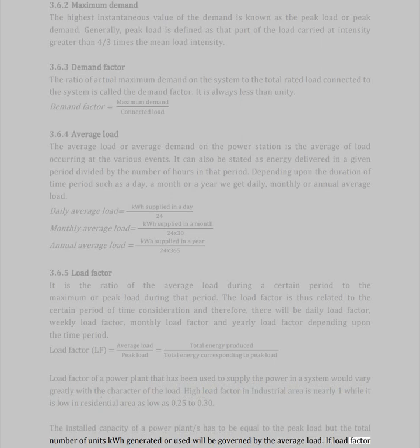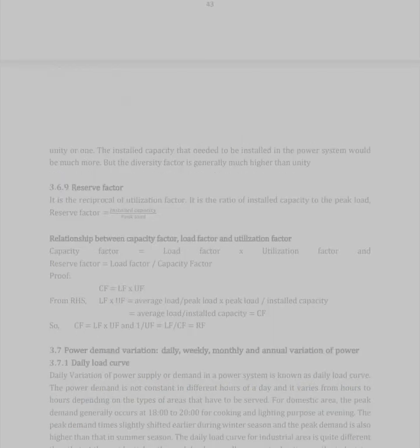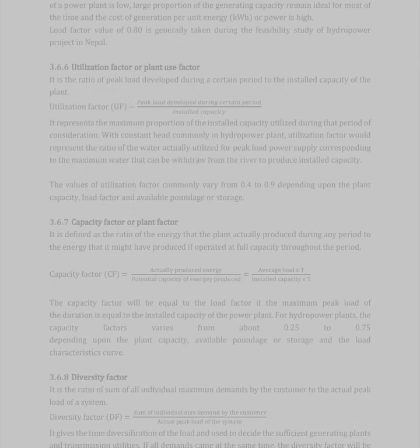If the load factor of a power plant is low, a large proportion of the generating capacity remains idle most of the time and the cost of generation per unit energy, kilowatt-hour, or power is high. A load factor value of 0.80 is generally taken during the feasibility study of hydropower projects in Nepal.